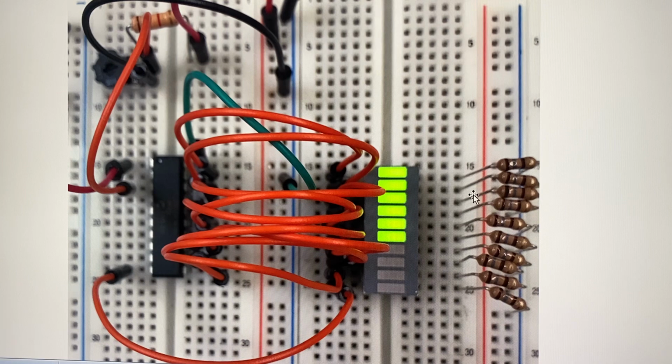Each LED requires 180 ohm resistors in this case, but it can be from 120 up to 400 ohms. So every LED has a jumper to port C and 2 more bits, which might be in another port, and this is the trim pot.